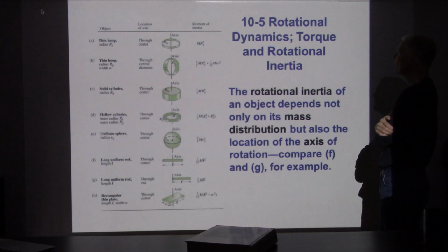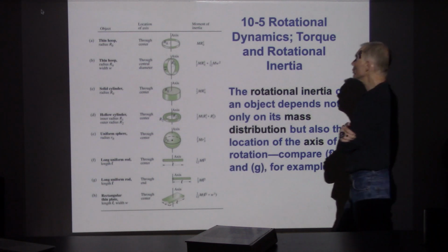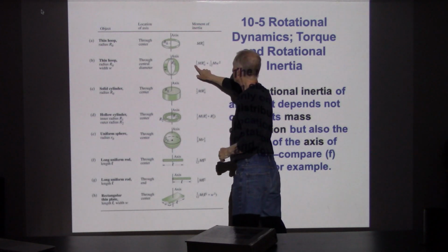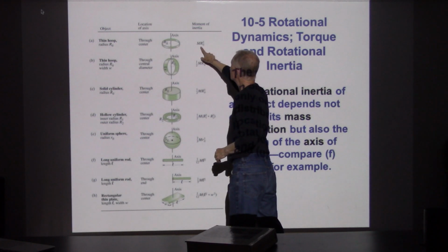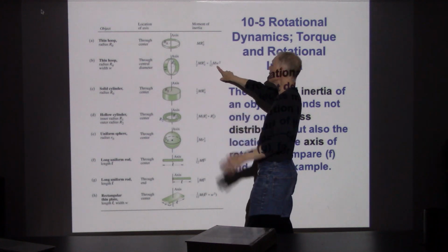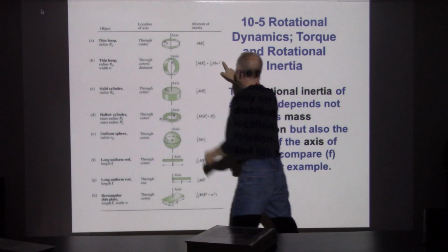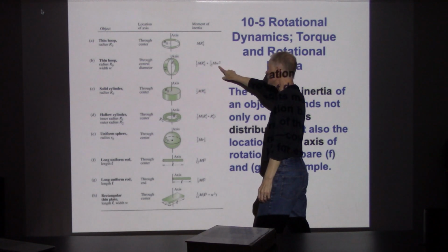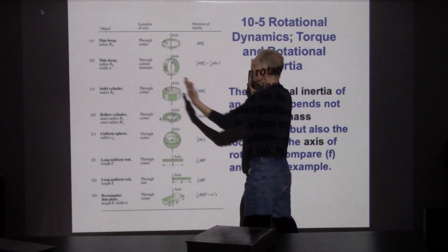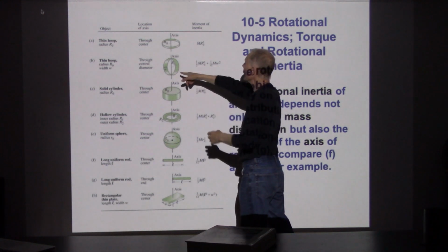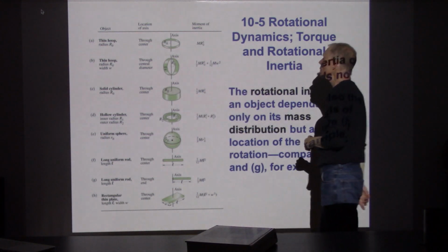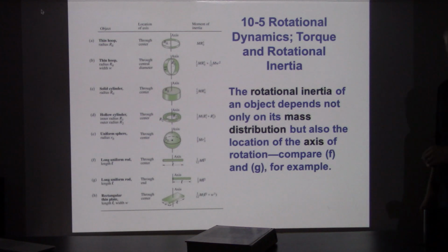Now it's 1/2 mr squared, which means only half as much inertia as before. And this term is saying it also depends on the width. If the hoop is spread out this way, that will add additional rotational inertia. If W was just tiny, negligible, then it would still be only 1/2 as much as the other orientation.